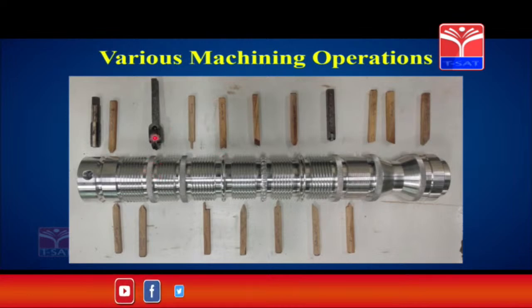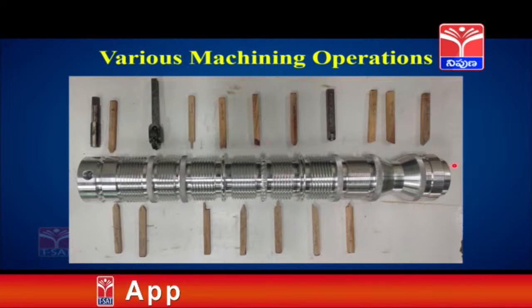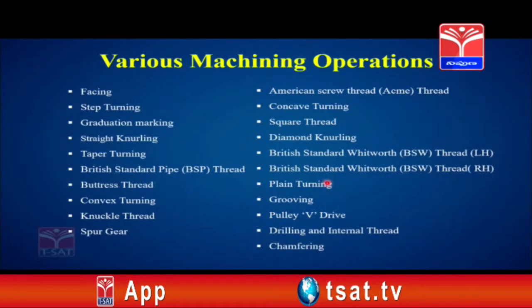Knurling tool is different. So, we have taken one single tool, we know the tool signature, and we continuously change this tool signature based on the operations, and we perform the multiple operations on a single rod. Let me tell you, almost 20 various machining operations we have performed by using one single tool and one machine tool, that is lathe, and HSS drill bit. These are the operations which we have just discussed.